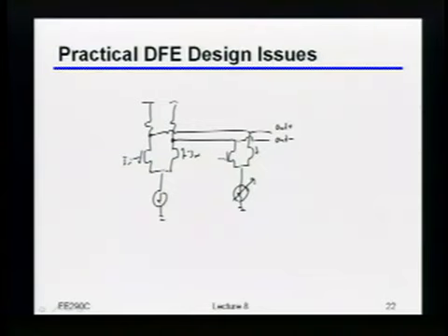Not only that, if there are a lot of those taps, as we'll talk about in a little while, I may need pretty high resolution in terms of how well I control the value of that current there. It may even be up to 6 to 7 bits, maybe more if you had a very large number of taps. Well, that tends to mean that this DAC here is going to be pretty big. In particular, building a 6 or 7-bit DAC is probably way bigger than the transistors you're going to want to use in this thing, where you want to pack everything in as tightly as you possibly can. Because it's your high-speed stuff, so any extra wire capacitance is just horrible.